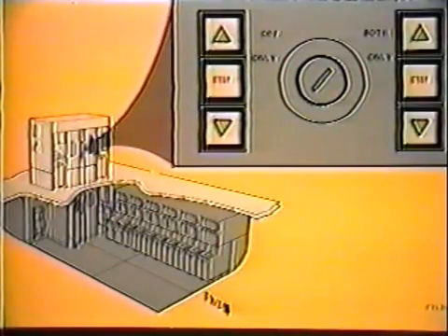Two galley lifts provide accessibility between the lower and upper galleys. They are fully independent and may be operated simultaneously. Each lift may transport either one service cart or one attendant in either direction. Internal controls are provided inside each lift. The external directional control switches are located on panels between the enclosures at both the upper and lower galley levels.